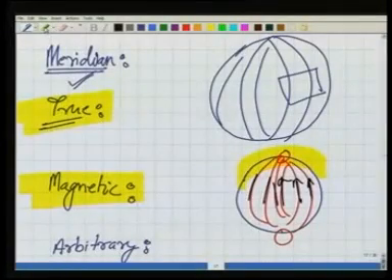We also use one more term that is called arbitrary meridian. Arbitrary means it is neither magnetic nor true. For example, right now I say, well, I have to establish a meridian, and I take any line from where I am standing, and there is a tree. Well, this line or this plane is a meridian, an arbitrary meridian. Then in order to measure any angles, I start measuring the angles from here. So I can establish these arbitrary meridians also there on the ground.